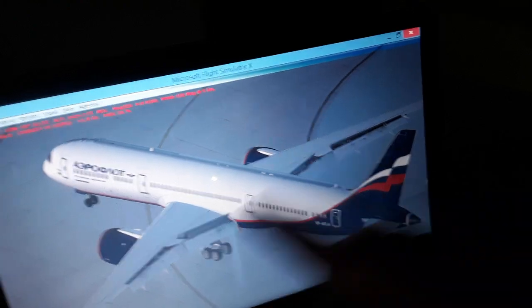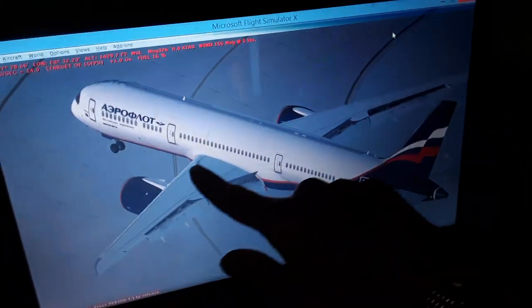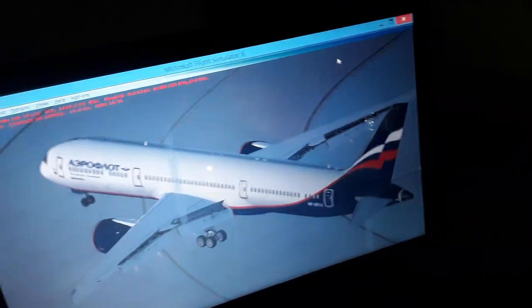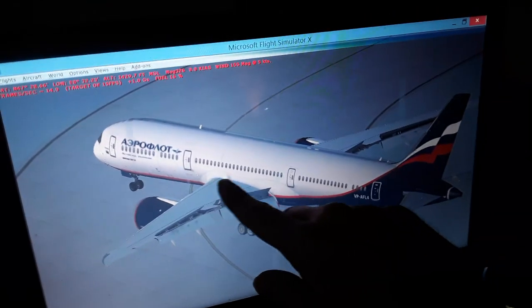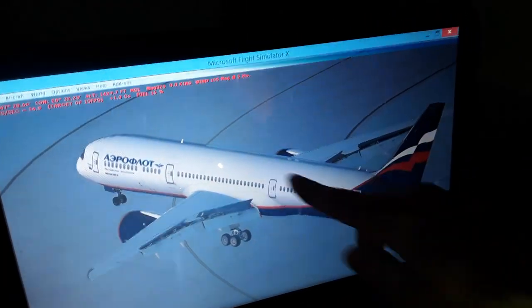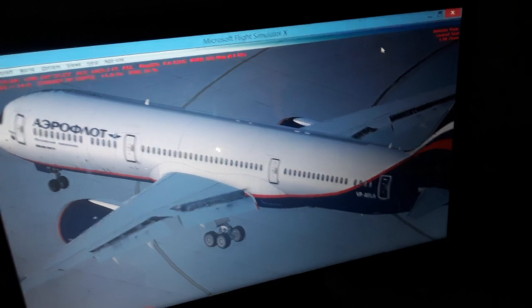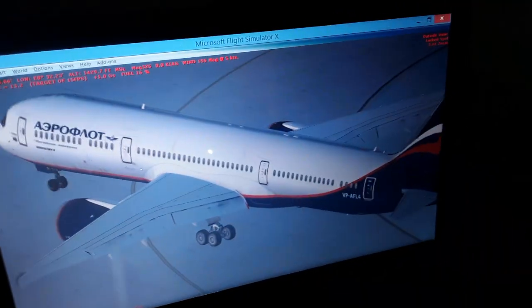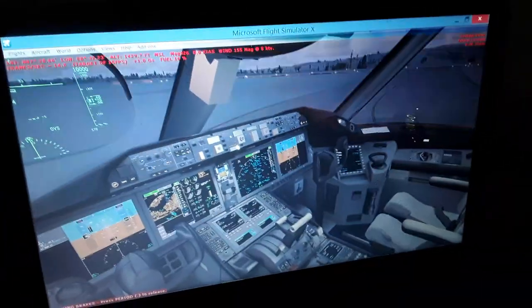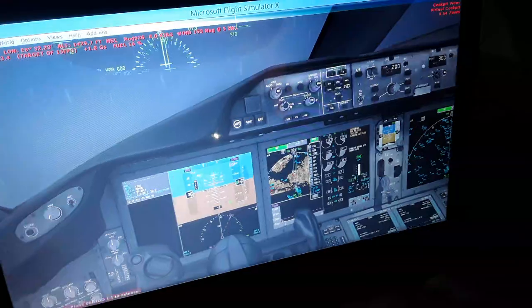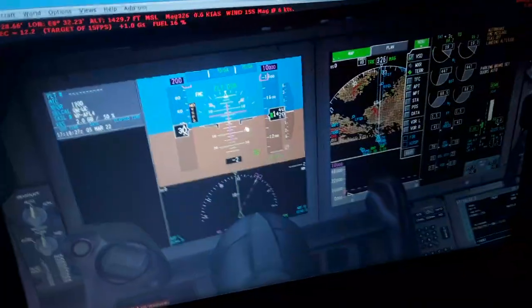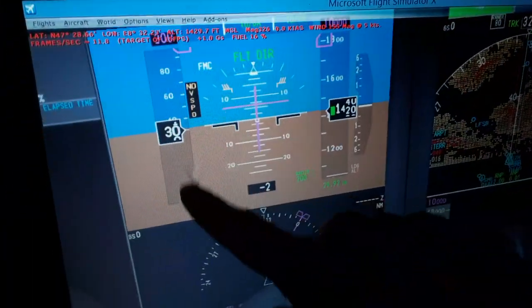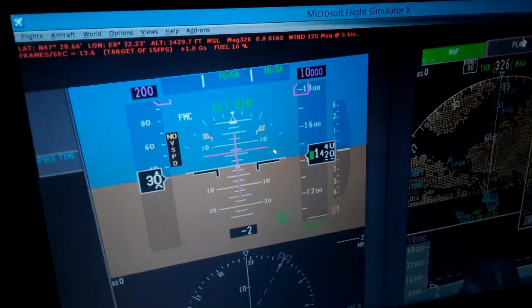We have the mean aerodynamic chord, where the maximum aerodynamic lift occurs, at 33% for this aircraft in this flight, where the center of pressure is moving back and forth. Also the stall: the airflow becomes detached from the top surface of the wings, and the wings stall for a given angle of attack and airspeed. So you need to monitor this in the primary flight display when we fly. You will see the stall speed indicated with a red and yellow indication below the airspeed when we fly. So we need to avoid the stall.